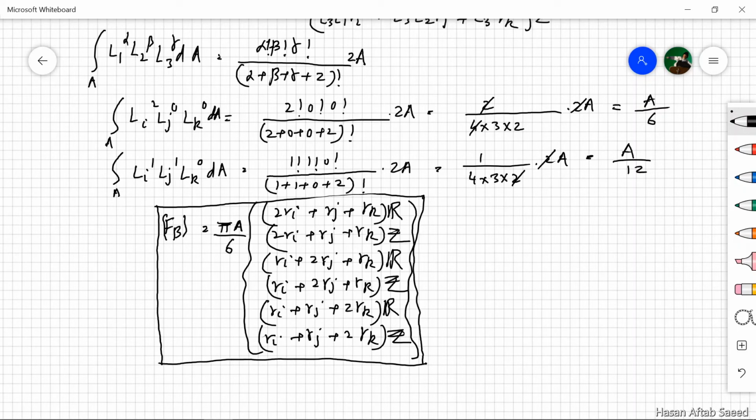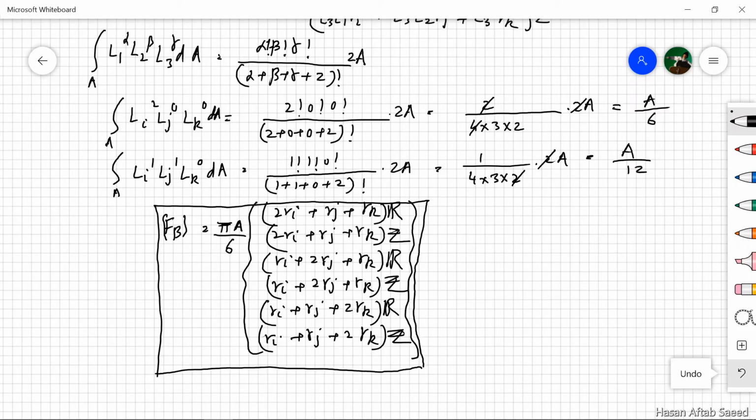Now note that the body forces are not distributed equally among the 3 nodes. Whichever is located farthest away from the origin will get the maximum value of the force. Indeed, that should be the case because there is more material at the outside than there is at the inside. So more force should be applied at the node which is farthest away from the center line.